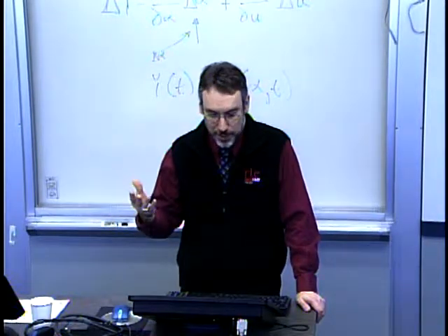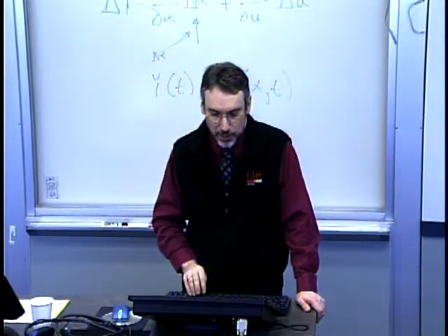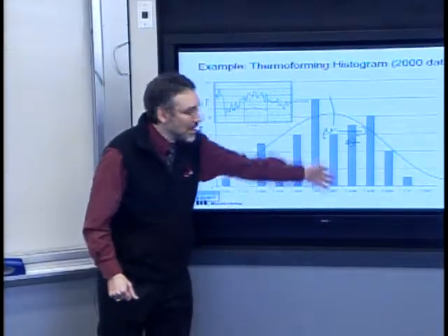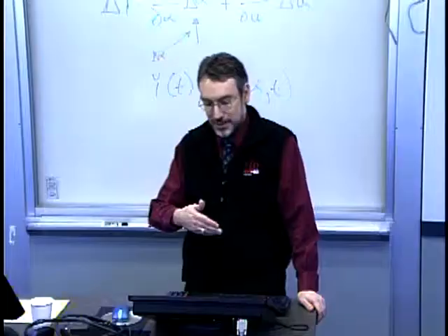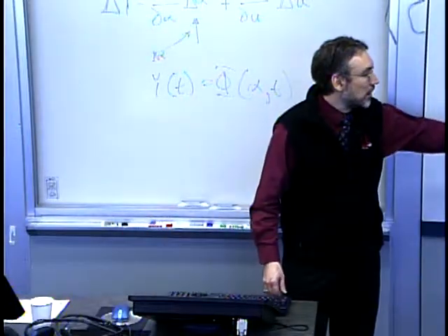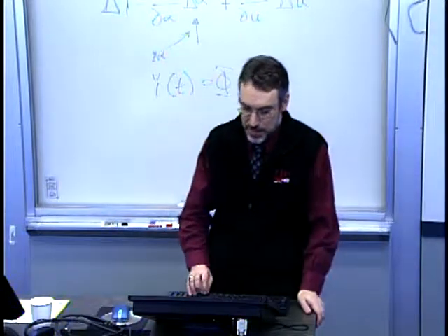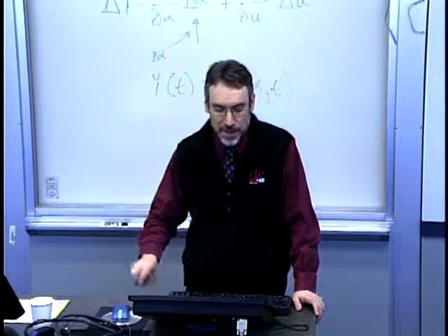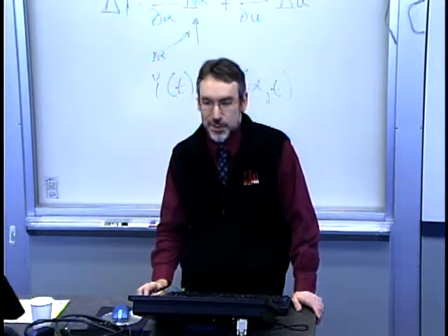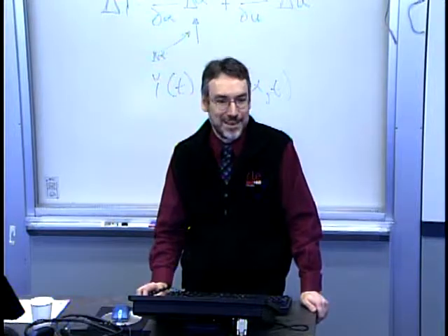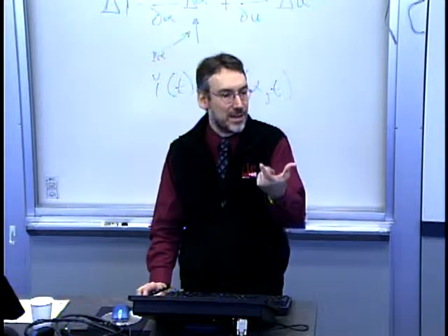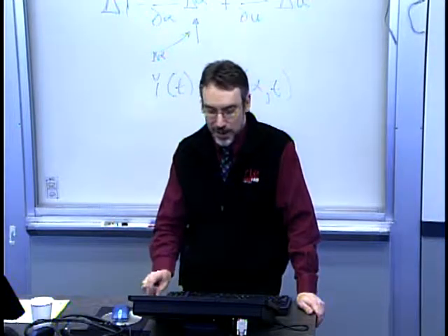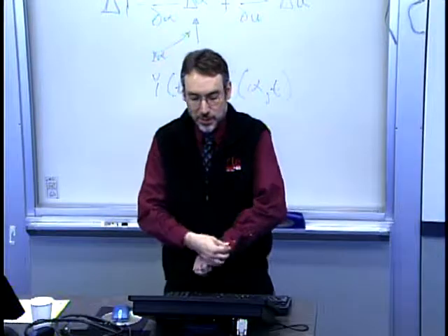So one important point here is we're often going to take this discrete binned kind of information and want to characterize it with perhaps a continuous parameter variable and a compact distribution, such as a normal or Gaussian distribution. And this is especially good when the outputs y are themselves truly continuous parameters, like a width, a dimension of the part.